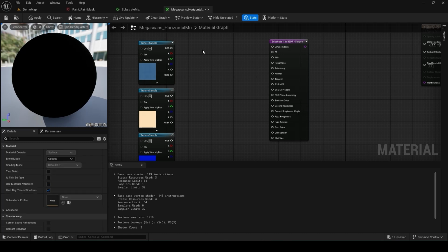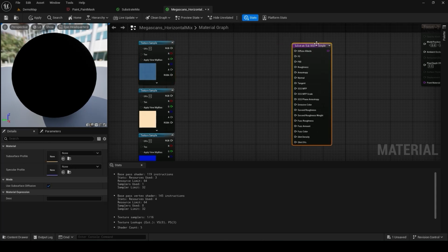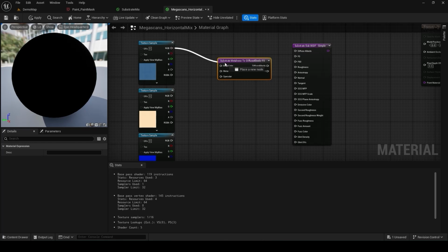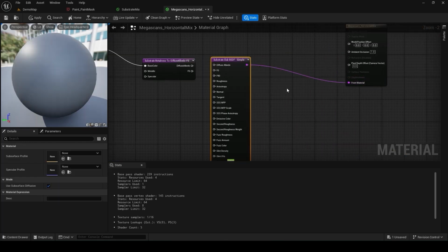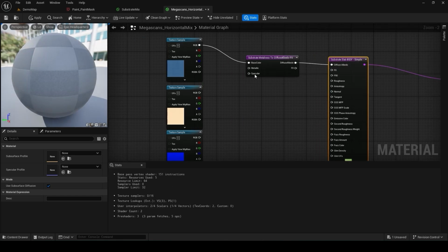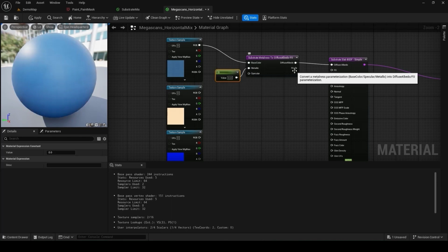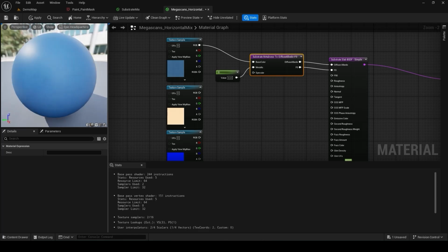So with my wall paint, I don't actually have a metallic map. So if I use this same Metalist F0 color here, I could just plug this in. And let's just kind of view this as I work. So I could just plug in my base color, and then I could just plug in 0 into my metallic, right? And that's essentially going to do the same thing.